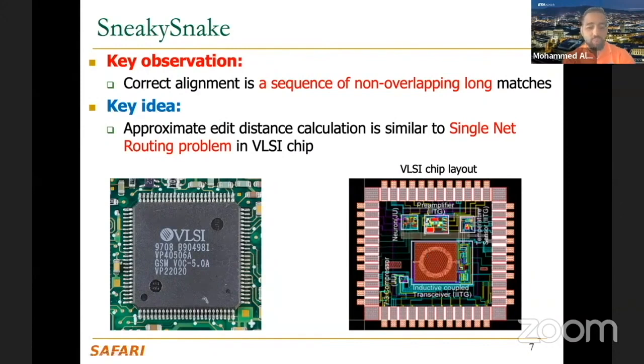Now, shortest path or lowest cost has multiple definitions. It could be the lowest latency, the minimum energy consumption, or the least routing cost, for example, because for these routing paths you pay a cost, right? And you don't want to increase their number because they will increase the energy or take space because they will collide with those modules. So your goal is to find the shortest path from one point to another point while connecting some of these components or avoiding these components. It depends on your design schema. So that is the single net routing problem.